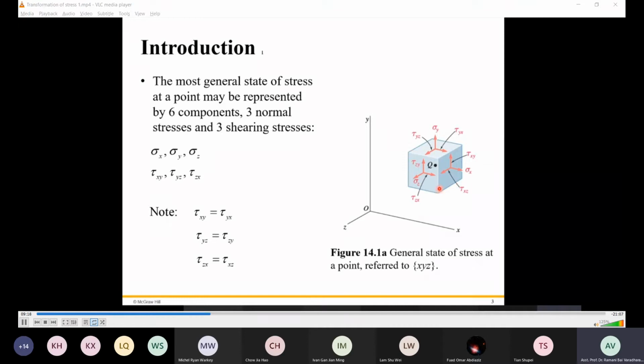And this side, similar to that, on the plane is the shear. Perpendicular to the plane is normal. Depending on the direction, you can name it. This is parallel to the z direction, z. This is parallel to the x direction, x. Same goes here. Parallel to the y direction, perpendicular to the plane, normal, sigma. And this one is on the plane. It's always on the plane, remember it that way. On the plane is the shear stress. And between which axes it is acting, then it is called YZ and YX, between this face and this face.